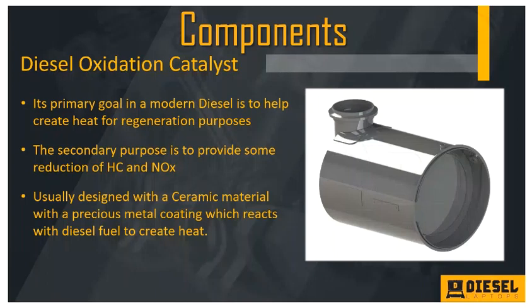In other words, they take a liquid that has aluminum oxide, and they dip that ceramic substrate down into that liquid. Think of that kind of like a binder or a glue or an adhesive, right? And then they're going to dip it, or what they call impregnate, this assembly with precious metals, okay? And what that means is they're going to inject or dip, depending on the manufacturer, precious metals inside of those cellular walls, okay? And they do that so we have something to react with.